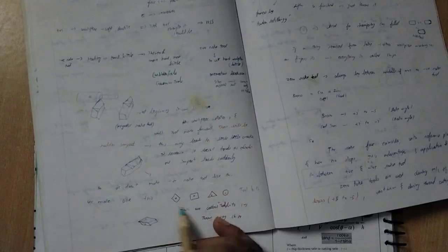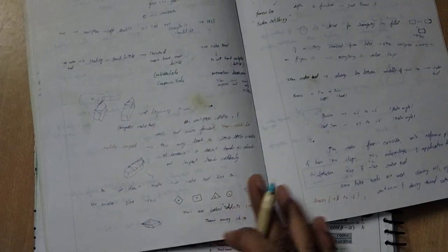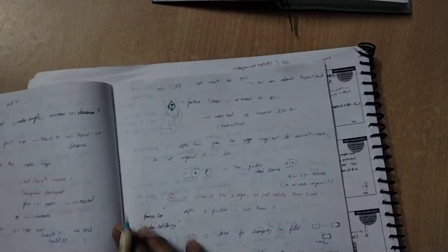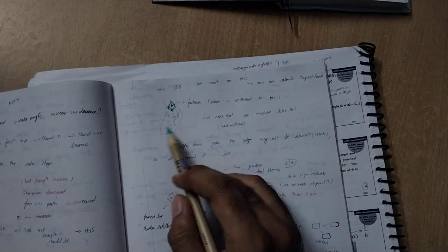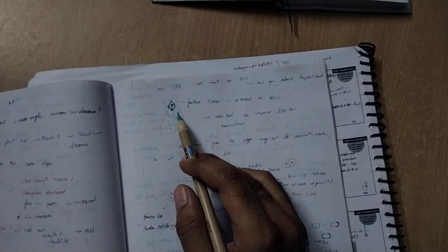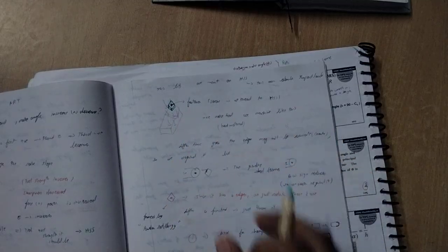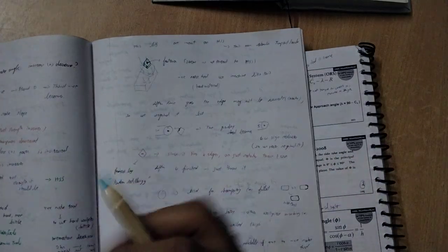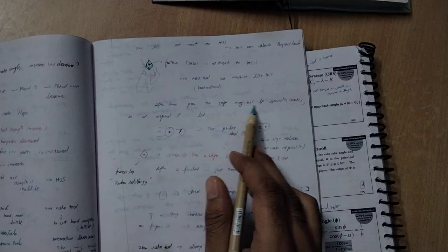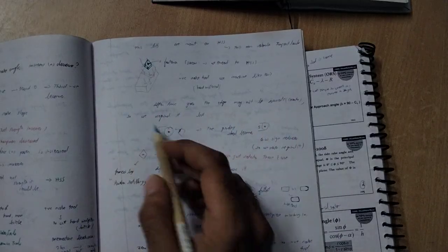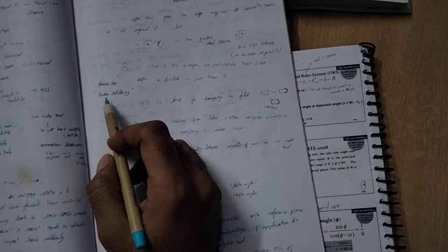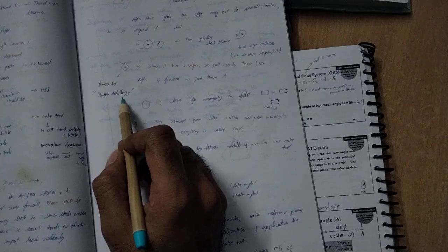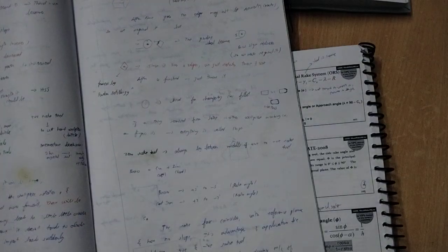You can see this entire tool bit is brittle material. With the fastener we just screw it, and with the thread we adjust. This entire thing is high speed steel. High speed steel has the capacity to absorb a lot of stresses and energy. After time goes the edge may not be correct, so we regain it, we just rotate it. Generally this kind of tool bit is formed by powder metallurgy. I think you can understand.